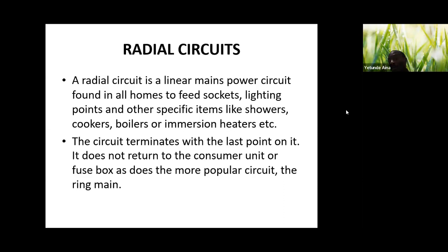heaters. For instance, if I want to do the connection of your boiler, I want to allocate a breaker for your socket. That can be done in such a way that I just allocate one breaker for that load, and that means in that circuit I will have just that point being controlled by that section alone. So that's a radial circuit.